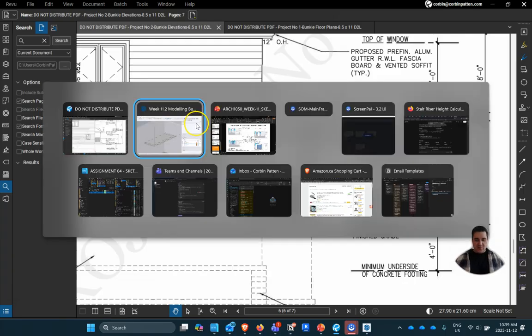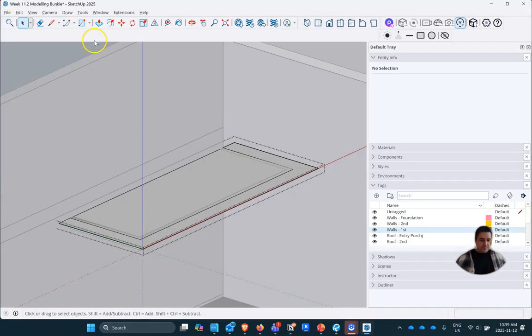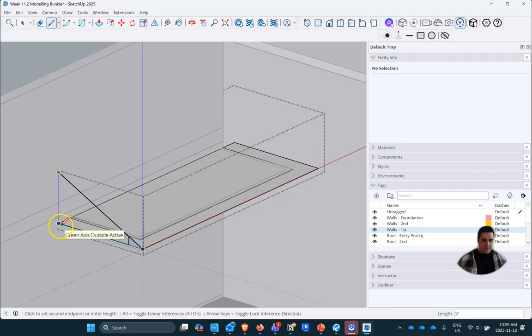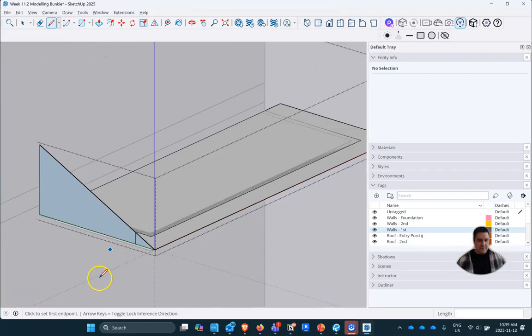So let's do our 6/12. And so we're going to go to our side here, and we're going to go over our 12 inches. We'll find that. We'll go up our 6 inches, like this, and then we'll extend this along our pink line till it gets to some sort of edge. In this case, it gets to the wall, and it did lock there nicely.